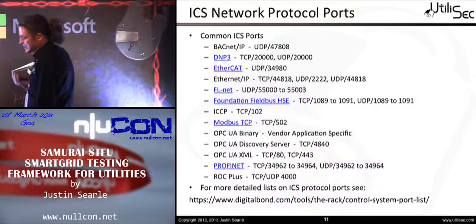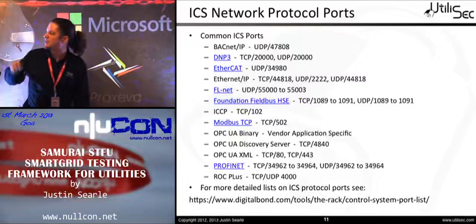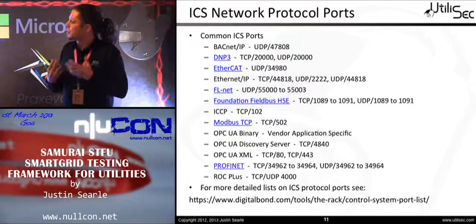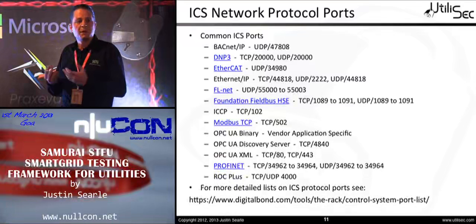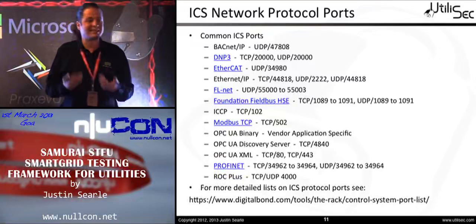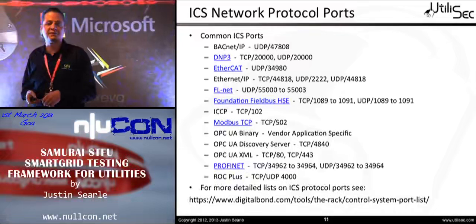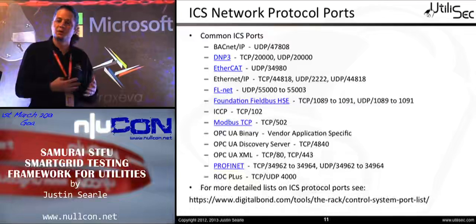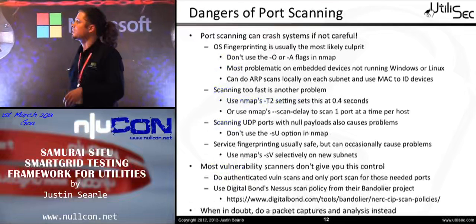We also end up needing to, when we do penetration testing on control networks, work with specialized protocols. Here's just a list of some of the more common protocols we have inside of the control center world. So one of the goals of our distribution is trying to provide different tools to work with each one of these protocols. Okay? Trying to provide fuzzers already set up to work with some of these different protocols, documentation, links to additional information, and most importantly, when available, different types of simulators to simulate these protocols so that we can work on using and testing our tools against the simulators before we go in and start trying to test them inside of real production networks.